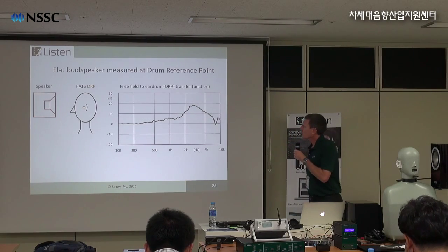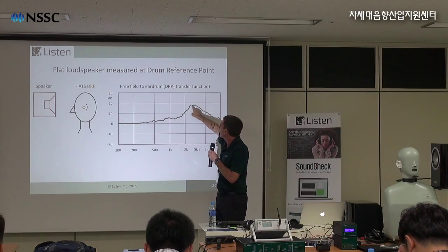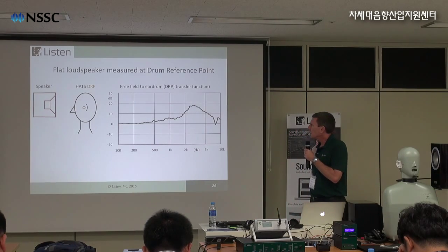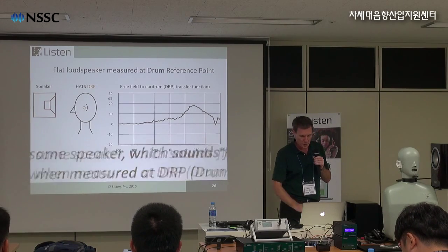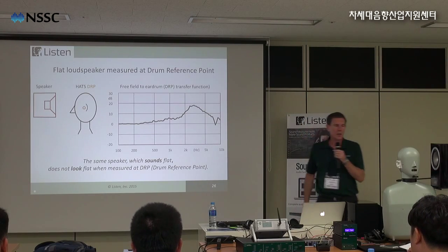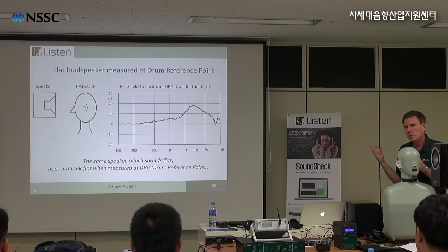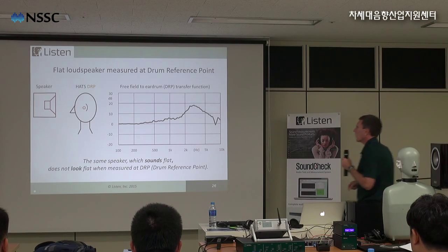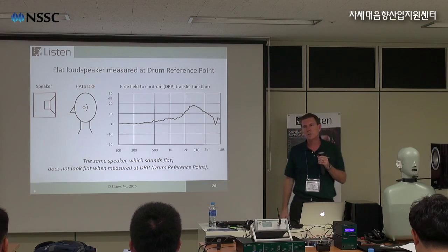And if we measure it, we now get this bump, kind of a squiggly line, up here, somewhere around 18 dB at 3 kilohertz. And you've got to ask yourself, why is that? Well, the answer is pretty straightforward: we have an ear canal, just like a real human ear, that has a resonance. Because we have this cavity inside, we get this bump, again like a real human ear, at about 3 kilohertz.